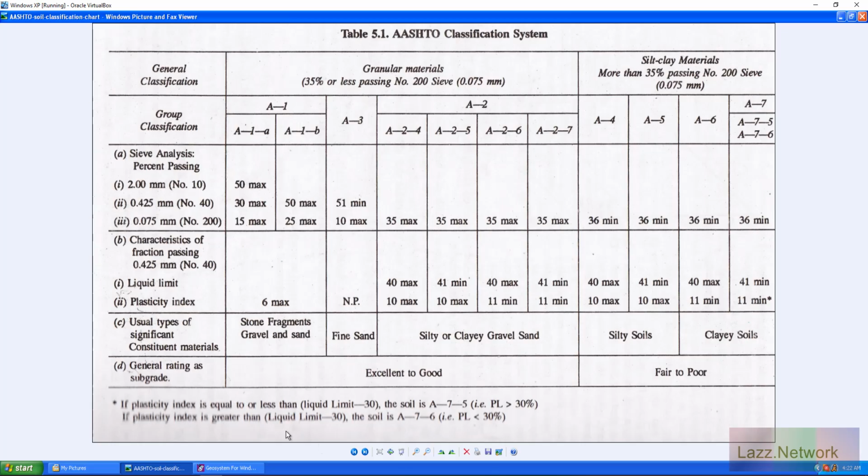Nah, it can't be plastic limit because if your plastic limit is equal to or less than, well, if it's equal to in general, then your value is going to be 0 for your plastic index. If your plastic index is going to be 0, it can't plot, which means it's non-plastic. I'll try to demonstrate something like that too, because that's very possible. Huh? That's very, very weird. I don't think that's 100% correct, but I don't know.